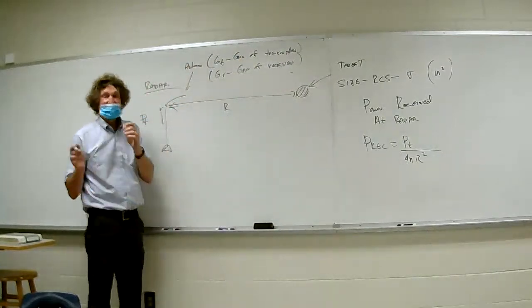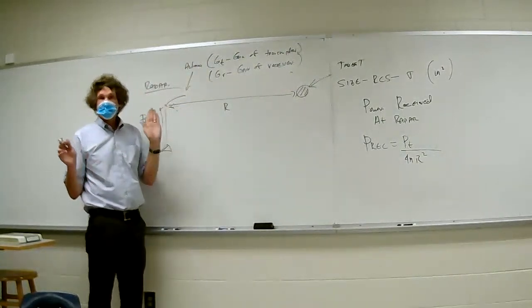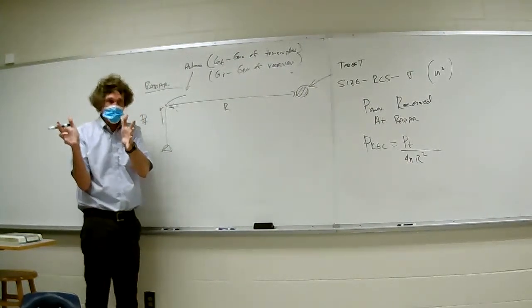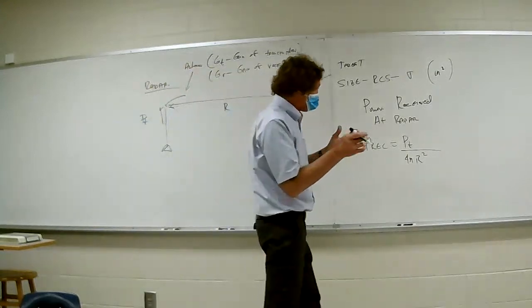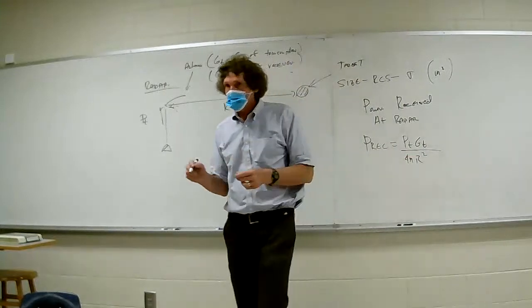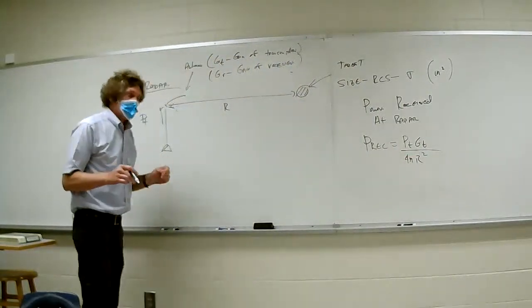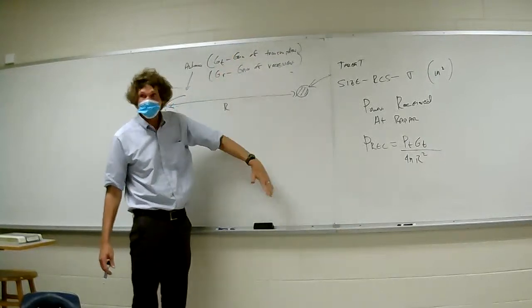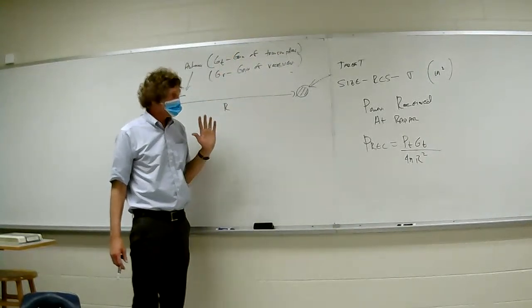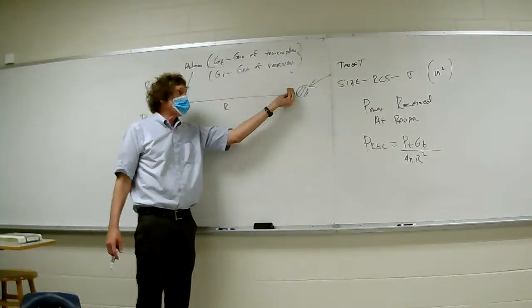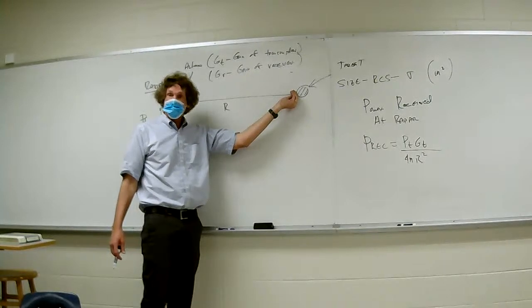But then the gain of the antenna, the transmitter gain, helps focus the beam, sharpen it. It increases the power density at certain points in the main beam. So it's the gain of the transmitter. Are you with me, everyone? Now I've got that power density, and if I know wherever the target is, the aspect angle and stuff, the gain will be a function of angles. I can adjust that. But now there's a certain amount of power that this thing is going to reflect back at me. Y'all with me?